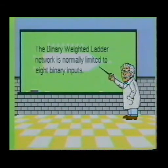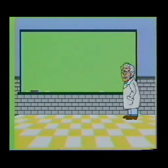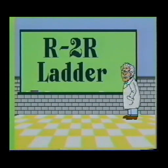The binary weighted ladder network is typically limited to 8 binary inputs. This is due to the fact that the value of the least significant bit resistor becomes too large, thus not allowing sufficient current to flow into the op-amp to facilitate a change at the output. Because of this limitation, the R2R ladder configuration is the most widely used of the two.